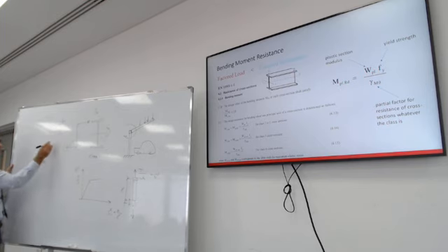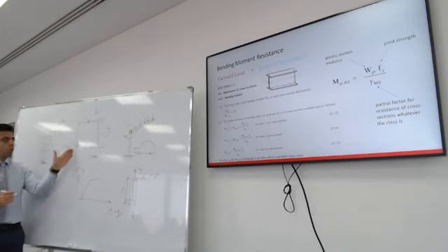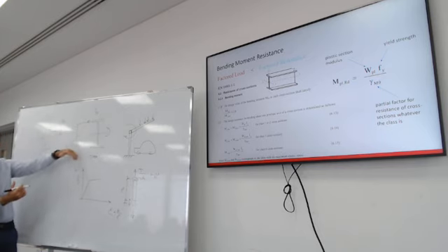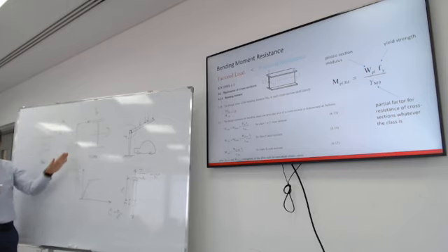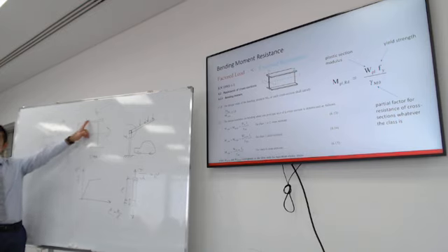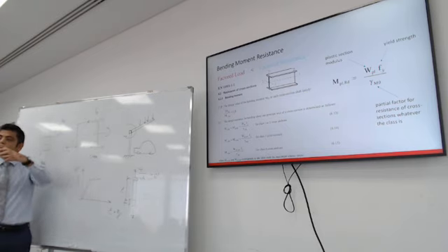And I can achieve tensile stress all the way to the yield to the neutral axis. So what these distributions mean is the bending stresses on the section. If the section is strong enough, it's class 1, and the distribution will look like this. It's yield everywhere. If the section is weaker than class 1, then I want to limit the top stress to yield and then have it in the elastic range. I don't want the section to be completely plastic.